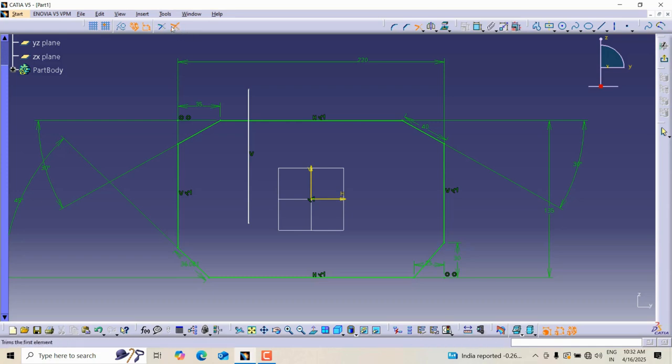I'm going to select the second type this time. First we have seen here. Select the line again and just extend it till the support. This time, if I click here on the opposite line or support line, the other side will not get trimmed and the line will only be extended this time. So it is only used for extending the lines, the second type.